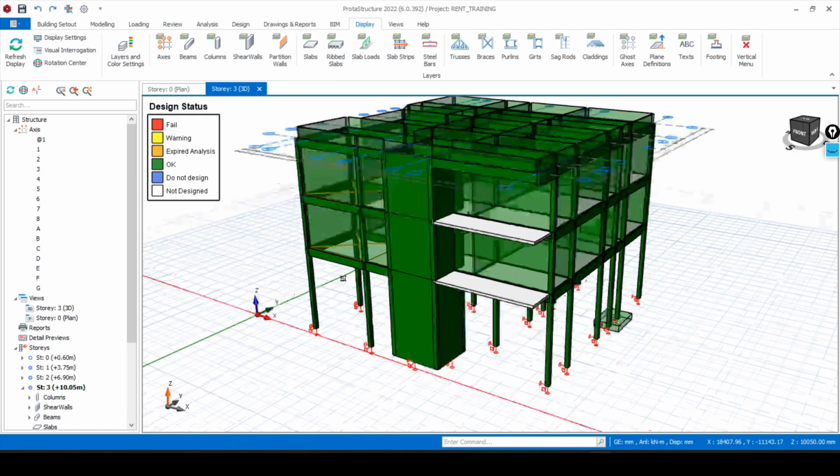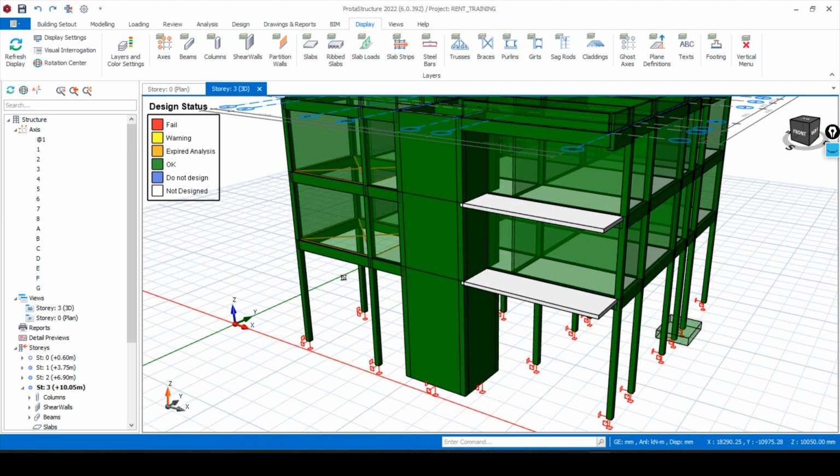Okay, what usually happens in our traditional construction sites is that we insert blocks in our foundation. That is just basically to contribute to the strength of our foundation. Blocks are not very strong members to be supporting your building. So what really carries your building are not the blocks that are inserted in the foundation. They just help to draft the layout of the building. Blocks don't even carry the loadings. So it's basically your columns and then your foundation, theoretically.